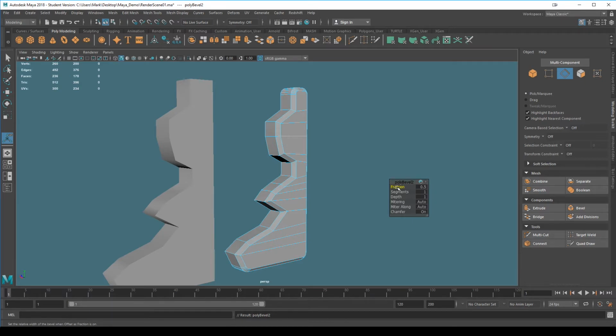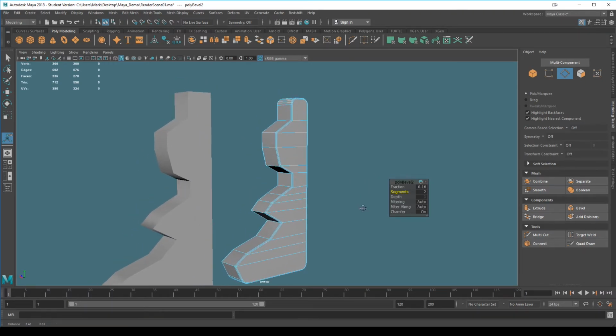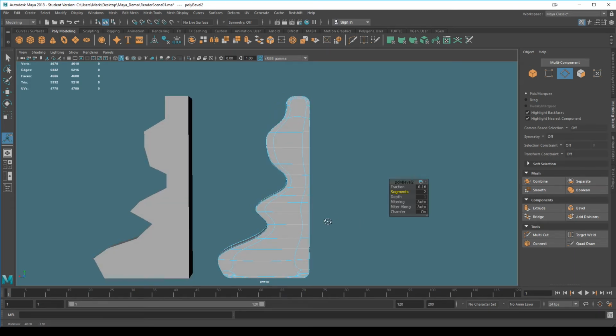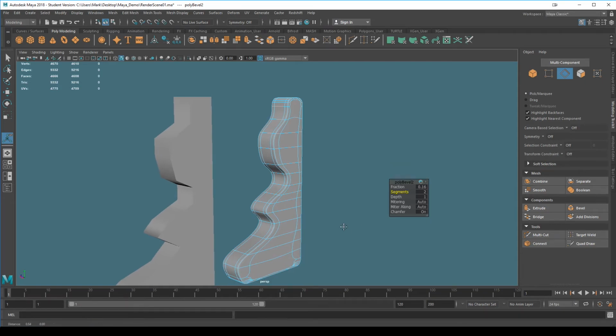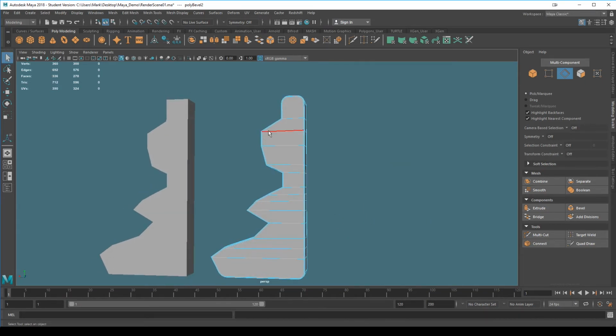and I'm going to hold down Control and click and drag on the word fraction to decide how small I want it, and I want this fairly small. I might give it just 2 segments, and before I move away from this tool by hitting Q, I'm going to just hit 3 on the keyboard and preview it, and then go, yep, happy with that, that's what I want. So hit 1 to get out of there and Q to complete that operation.